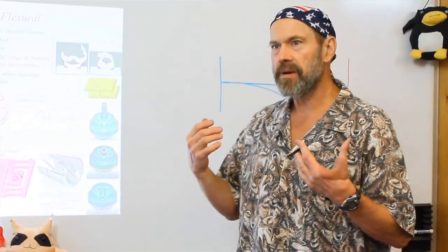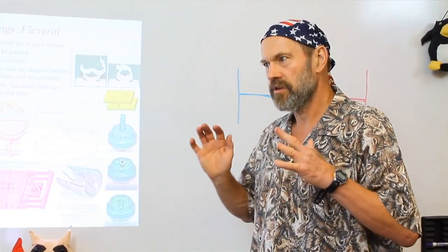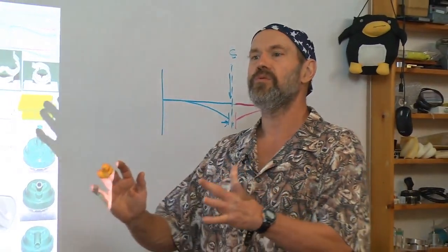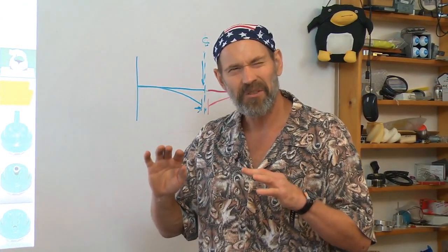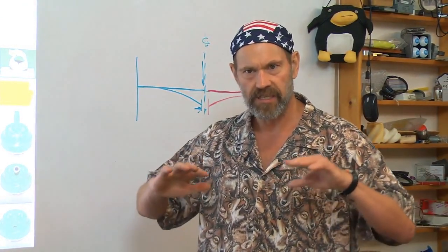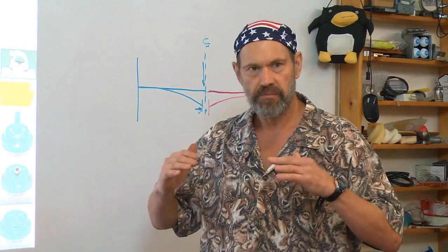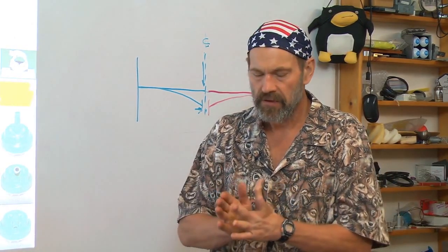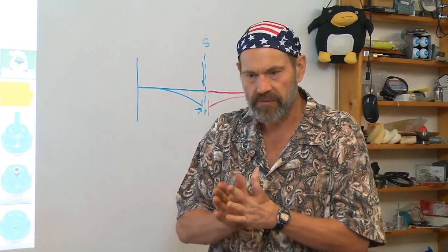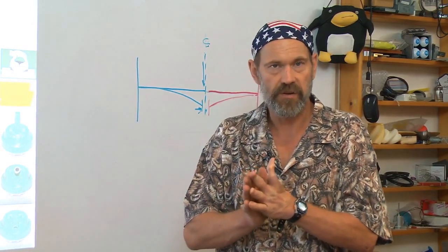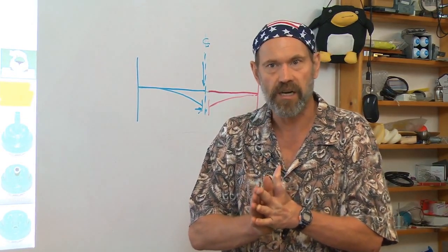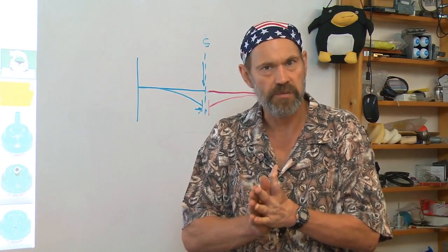This thinking about how bearings deform in the way you want them to move, and always being cognizant of what other little things are happening as things are moving, these parasitic motions, and being able to predict them, and being aware of them, and then determine if they're a problem for the functioning of your machine or not, is critical for the design of robust machinery.